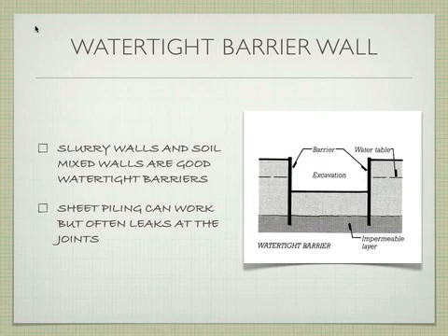Note that this would obviously be a really expensive thing to do because the slurry wall is much bigger than it has to be, which you can see from here. It's almost twice what it needs to be. Does that make sense? But it does work if you don't have any other option.